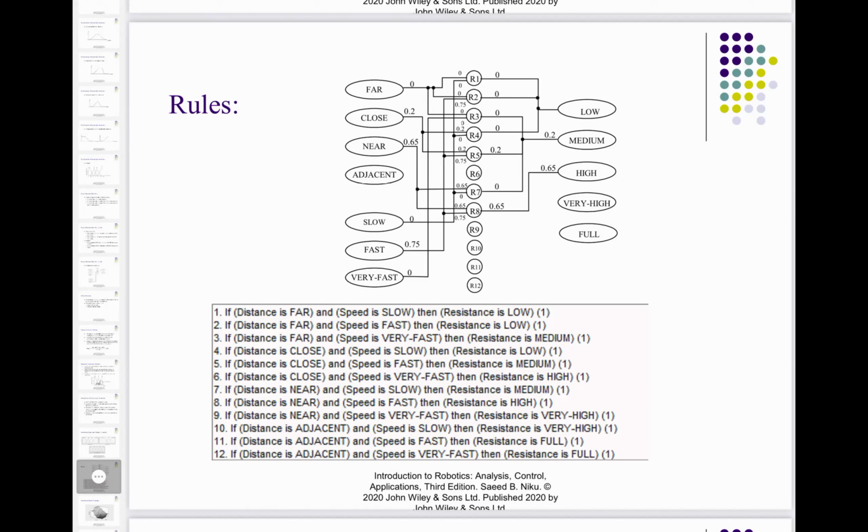So what you can do is construct the fuzzy logic rules based on your linguistic interpretation and then implement the controller. For example, if the cart is going towards right, and the pendulum is going towards right, if I want to make it upright, then clearly I want to apply the counterclockwise torque.